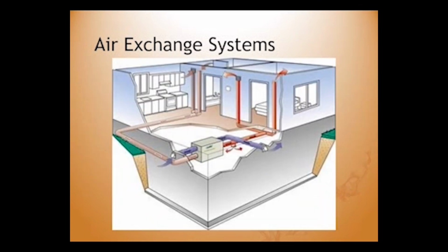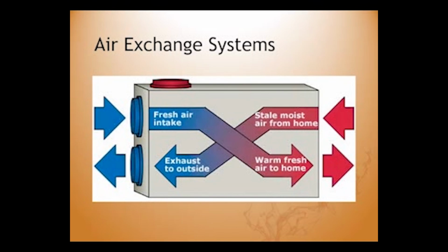If a building has a dedicated air exchange system, the fan is located in one location with ducts going into each area for air circulation. Turning on the common exhaust fan will cycle air in all the bathrooms in all the locations at the exact same time, and these are typically interlocked with the furnace and the HRV unit. The HRV unit is needed to heat any air brought into the home. It uses the heat inside the exhausted air and transfers it to the incoming air from outside. That way, we have preheated the air before it enters our system.